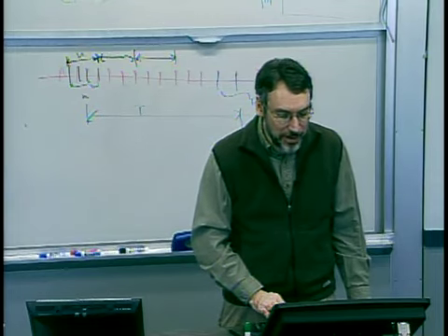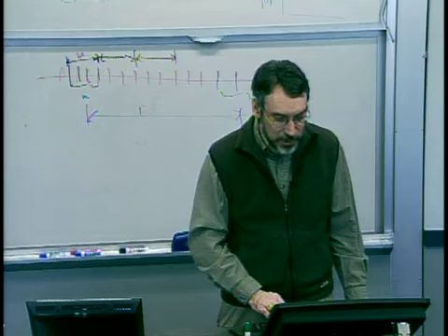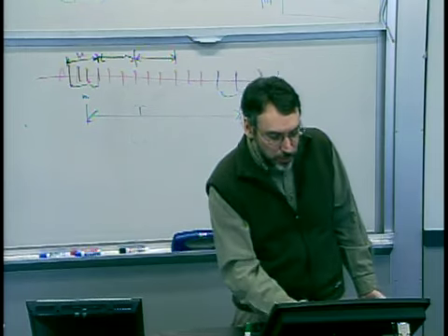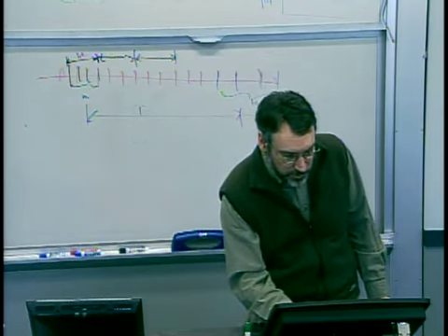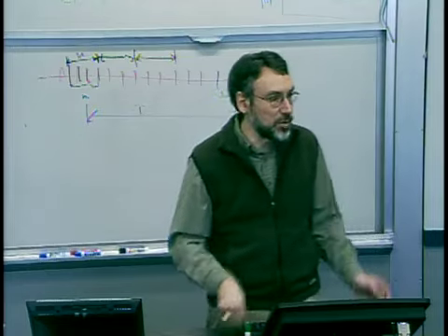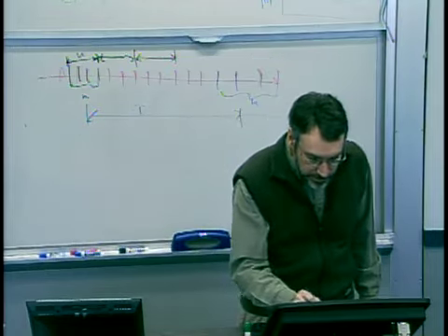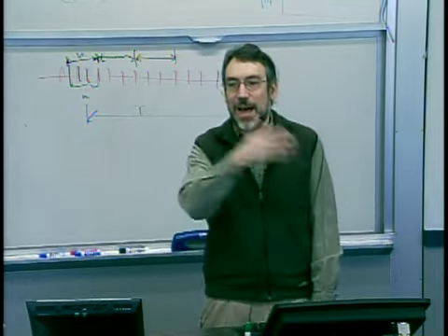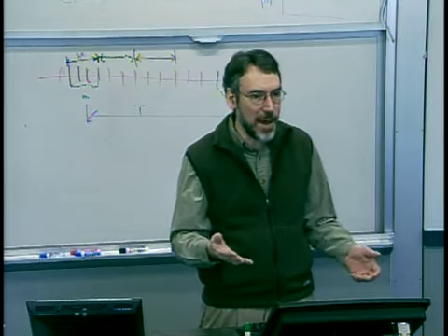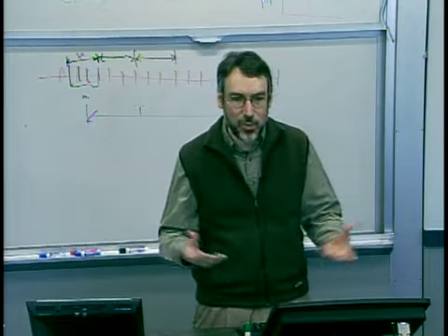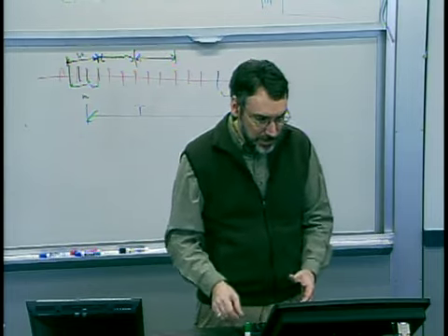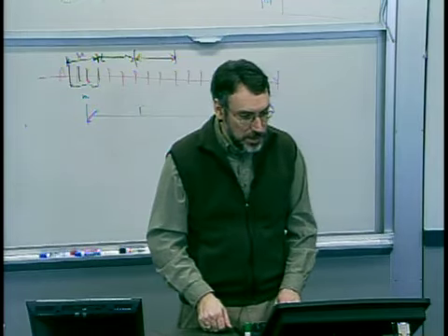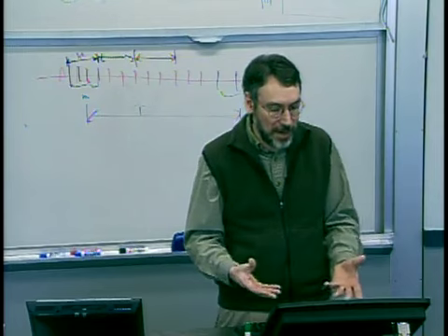Now, one can also go back, and if you're given the quality loss function, you can also ask if you have the probability. So think of this as the PDF. If I have the probability distribution function, I've got my underlying process with some mean and variance. You can also do that integral and ask questions about what is my expected quality loss, and do the same kinds of things for mean deviations or variance changes. You just have to go in and essentially do the calculation.